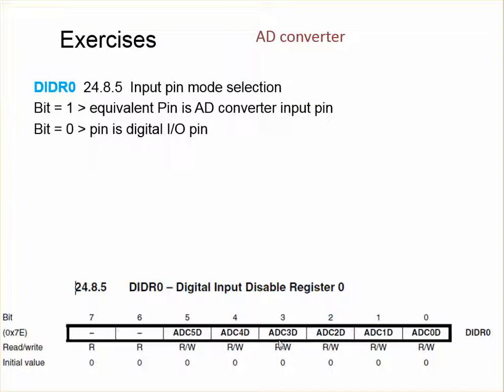So it means that with these bits we define the meaning of the input pins. Are they used for the digital C port or for our AD converter?